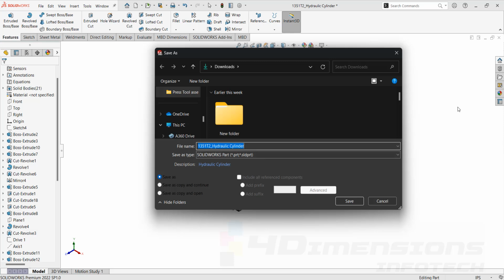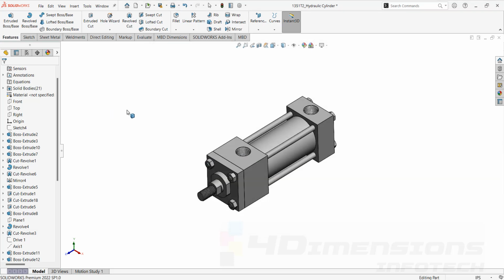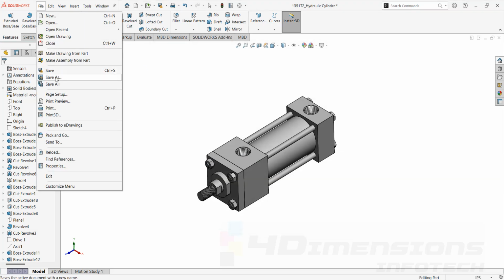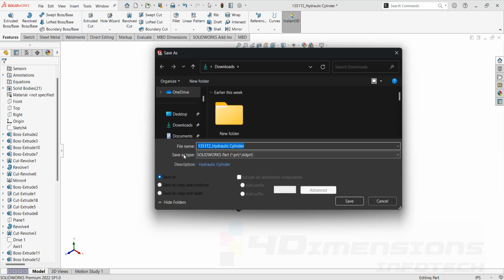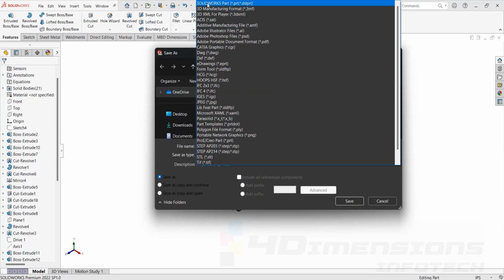Many times we require step file. So if you want to save this format as a step file, you just need to go say save as, and then select the save as type here. I'll repeat this again. Select the file option, say save as, and here you need to change the save as type. I'll select this and go and say as step AP214. You can also use 203. These are nothing but two formats of step files only. This is the older version and this one is the newer version. So I'll select this 214.